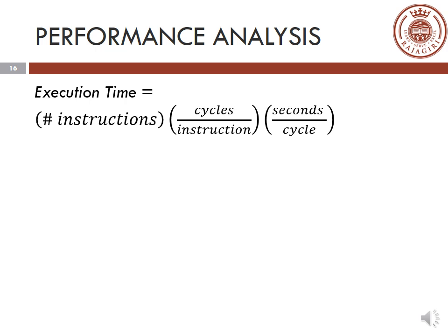Whenever you speak about performance analysis of a processor, you should be aware that processor performance is always associated with execution speed or execution time. The execution time should be reduced, or the execution speed increased. Performance analysis is defined in terms of execution time and given by an equation. Execution time here means the time required by the processor to execute a program, a set of instructions.